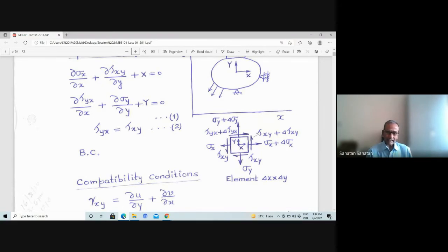So these are the stresses in the body which is in static equilibrium, and this element is subjected to stresses by the remaining body, as indicated. These are the forces acting on this element. Now there is also the possibility of some other forces, which I have shown on the sketch. The stresses are there on the boundary faces, but this element can also be subjected to body forces or volumetric forces. If you think of a plate hanging, it will have gravitational forces, and these gravitational forces will have components in your selected Cartesian directions x and y.